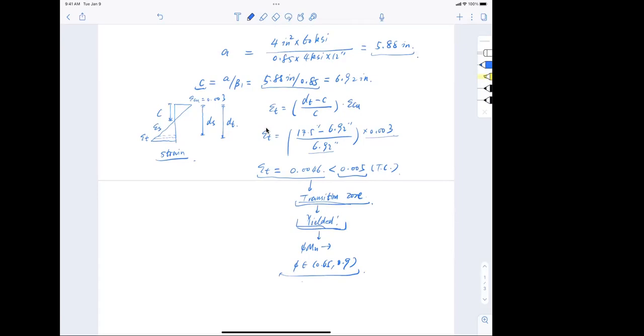Because you put a lot of steel in there, your total tension force is high. So you only need a smaller area for compression to balance that, and then you end up with a low strain in the steel. When the strain in the steel is low, you're not fully utilizing the capacity of the reinforcement, so you over reinforce the section. When we're under reinforced, that's the zone we're in whenever the compression and tension are supposed to balance out.